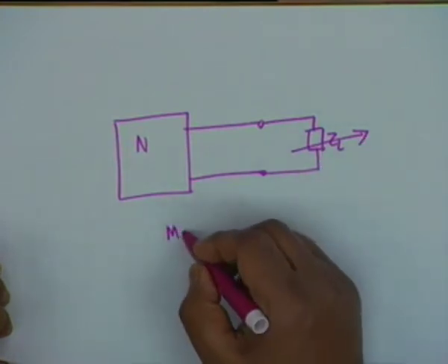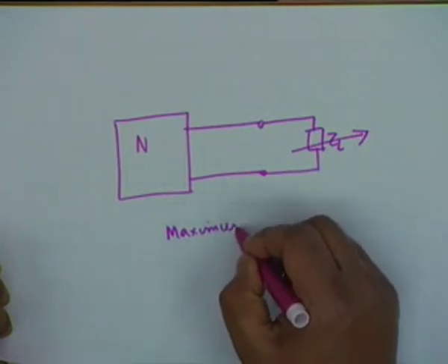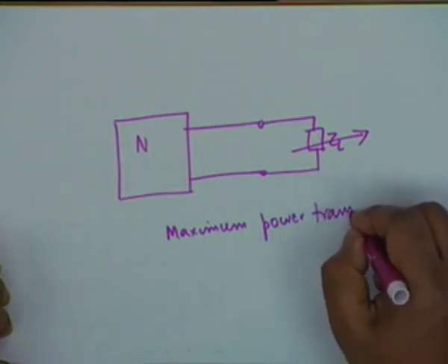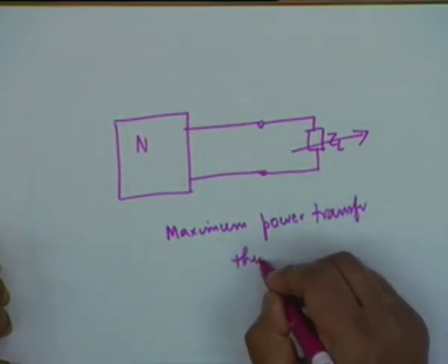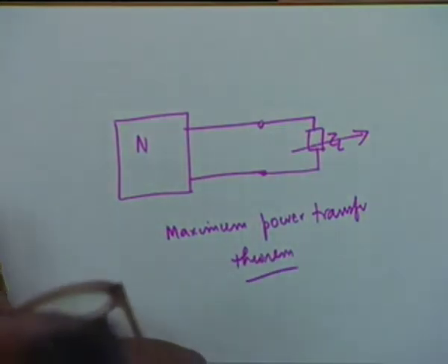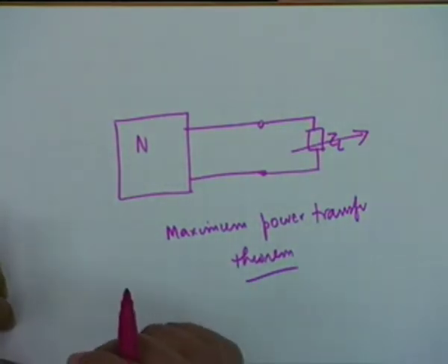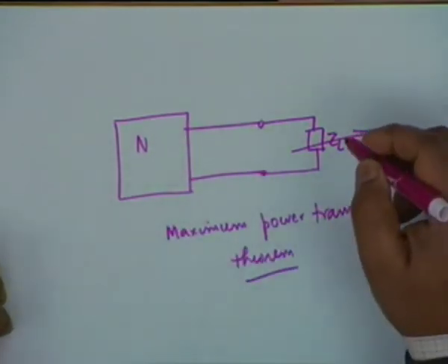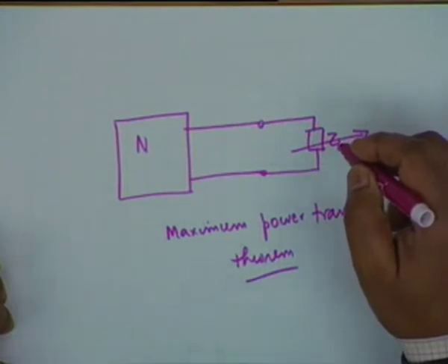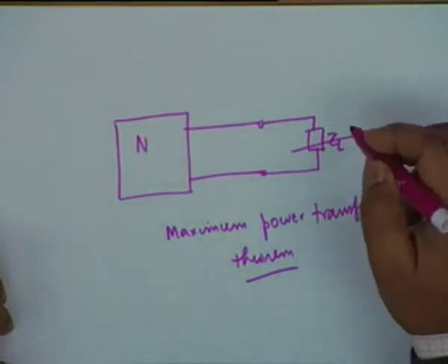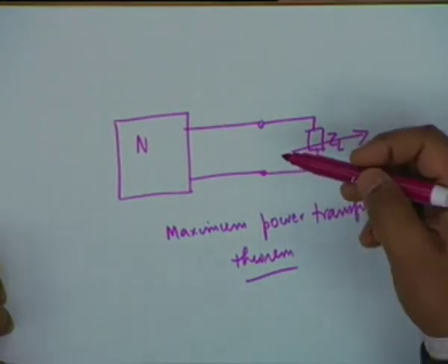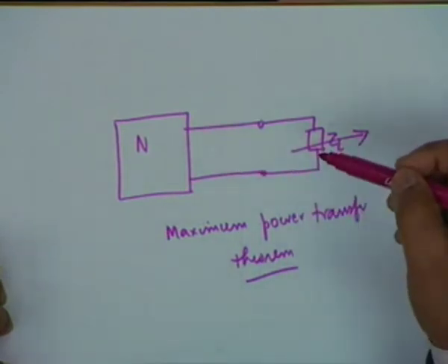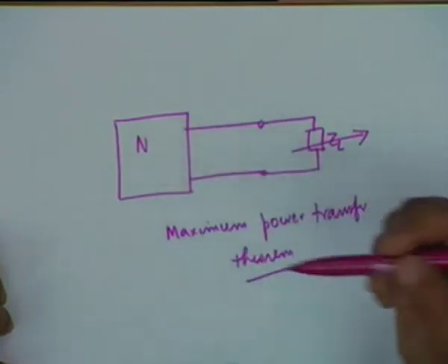And this is in the literature known as the maximum power transfer theorem, or simply maximum power theorem. It's very easy to show that if the network was resistive, then the load should also be purely resistive and should be equal to the Thevenin equivalent resistance of the network. This is the condition for maximum power transfer if capital N is resistive.